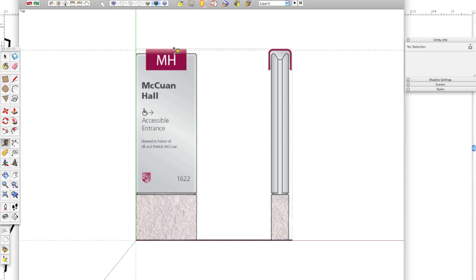Oh, I did an error there actually. With the tape measure tool, when you click it, see the little plus sign is checked on the cursor? Use option to turn that off. That way it doesn't create a guide, it actually just measures. And now this time let's actually measure. It's right about there. 5 feet 1.5.